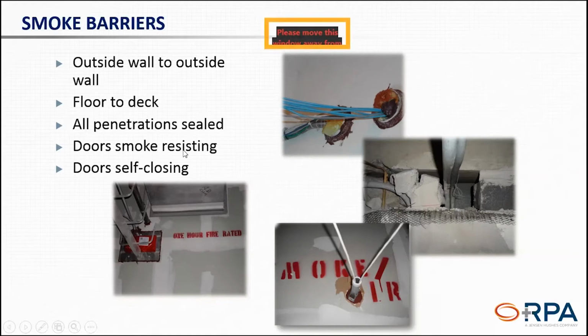We have smoke resisting doors, and those doors are self-closing. You don't see anything about latching hardware on smoke barrier doors because that's not required in healthcare. We do like to say that if you have latching hardware on your doors, they need to function. So just because it's not required doesn't mean it can just be hanging off. If you have the equipment there, it should be working in working fashion.